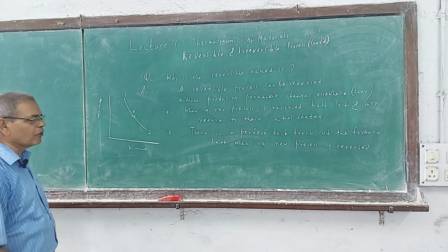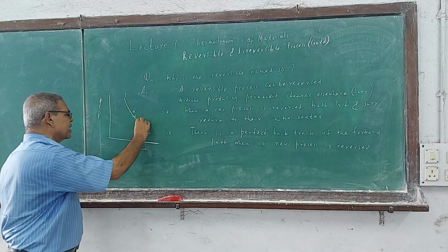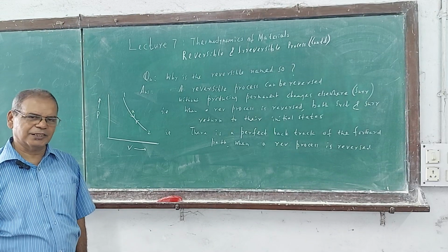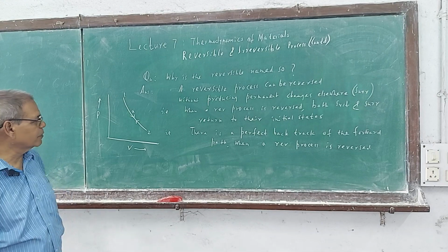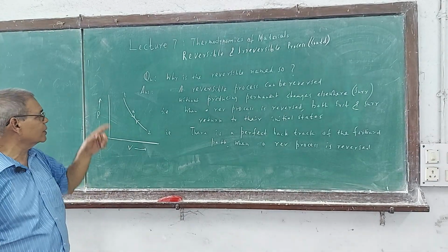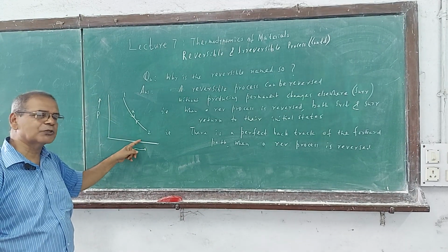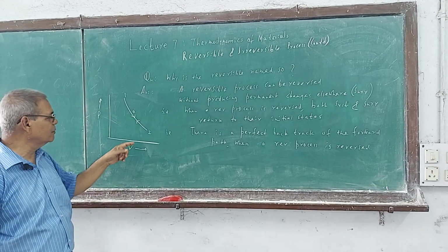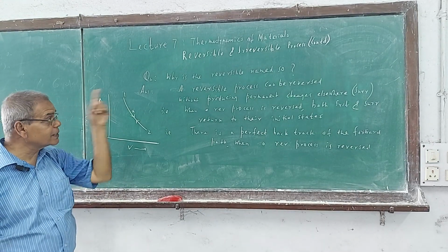If I want to take the compression, reversibly coming back to 1, it will retrace the path exactly, not drift from it. This is the beauty, or characteristic, of the reversible process. Forward is expansion, backward is compression, or in other words, the system moves from state 1 to state 2 through 1A2, and returns from 2 to 1 through 2A1. Exact reversal, hence the name reversible.